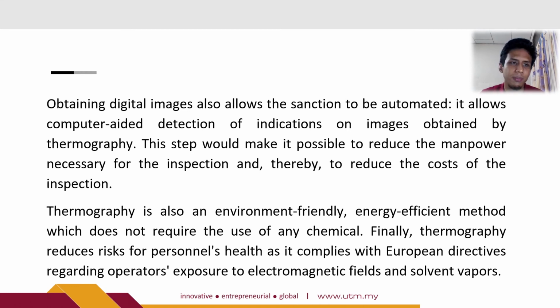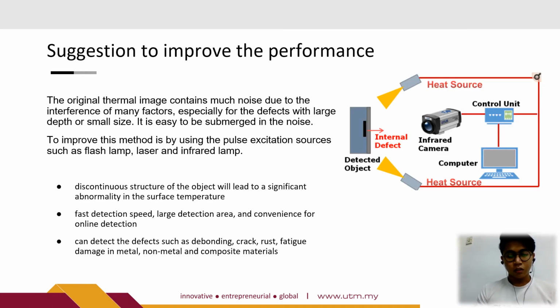Okay, now we proceed to the suggestion to improve the performance of this infrared thermographic method. The original thermal image contains much noise due to the interference of many factors, especially for defects with large depth or small size. Due to the small temperature difference, amplitude difference, and phase difference, it is easy for them to be submerged in the noise.